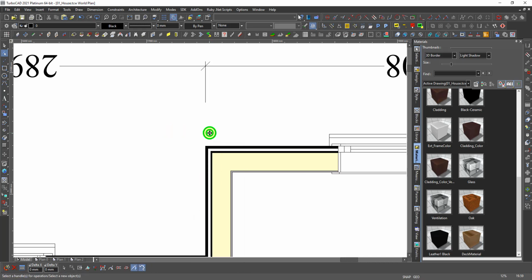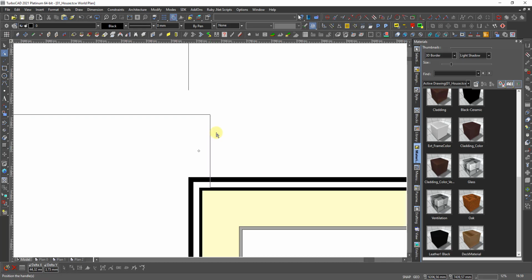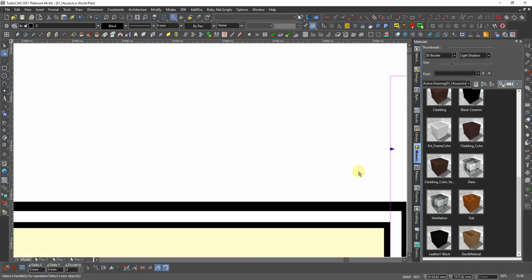I want this 98 millimeter more out here, because I plan to use a 98 millimeter piece of wood there. So then I tap, it will be in X, 98, 0, and enter. And the same thing here, I take this, minus 98, 0, and enter.